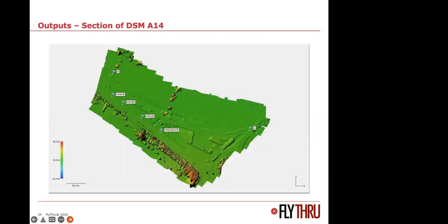And this is one of the 3D models that we produced. You can see there are various pits and structures. The surveyors were able to do the quantification from that. We were down at 1.5 centimetre accuracy on the ground, so that their volumetric analysis was plus or minus 4% of the actual material that had been moved, which was phenomenal. They were certainly a little bit opposed, I think, to using UAVs at the beginning, but when we saved them the money that we did, they're used extensively now by these guys who ask us to come and do the volumetric analysis for them.